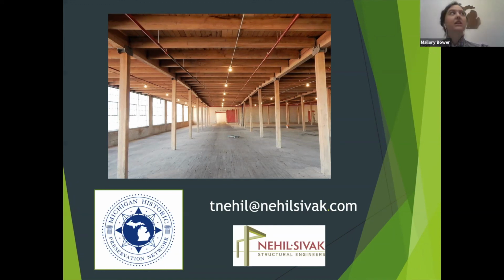Excellent. And then what species of tree is used in the posts, or is it similar? It's kind of whatever is on the property. Well, in fact, as you go back into the 1800s, that typically is the case. So in any one barn, you might come across oak and ash and elm, five or six different species used in posts. And some oddballs like basswood. Basswood used for beams and joists.